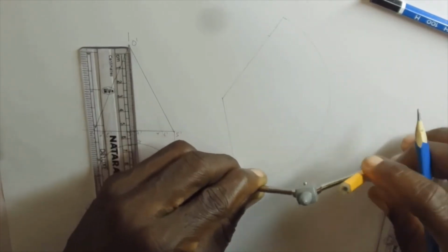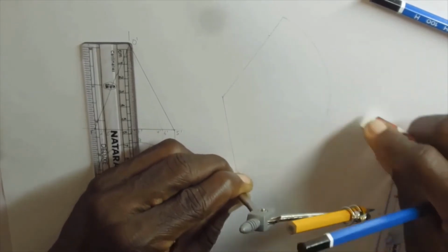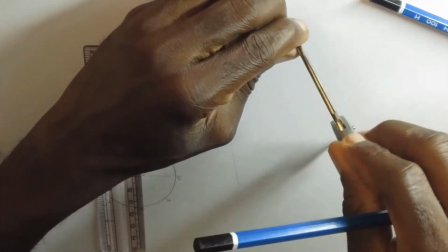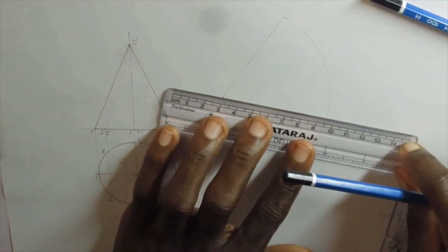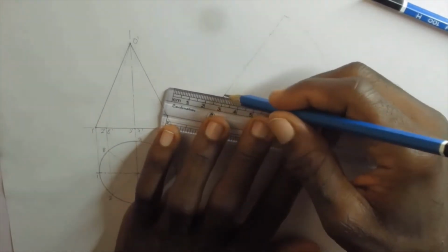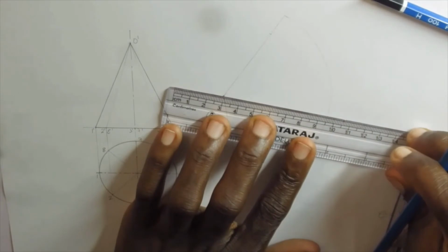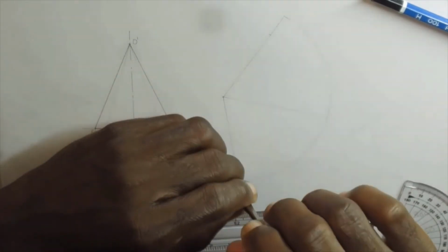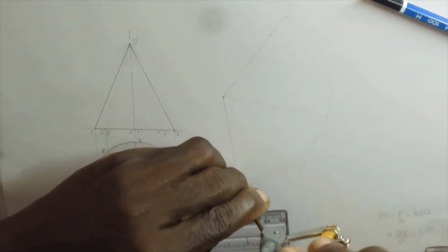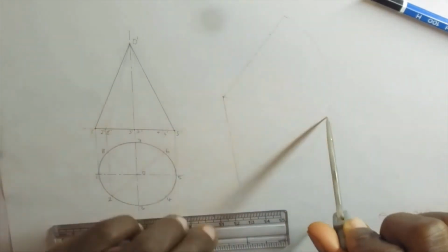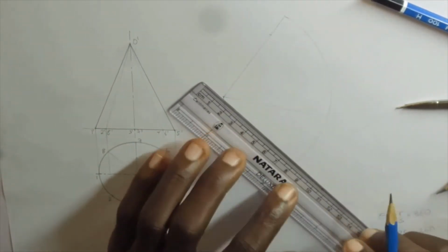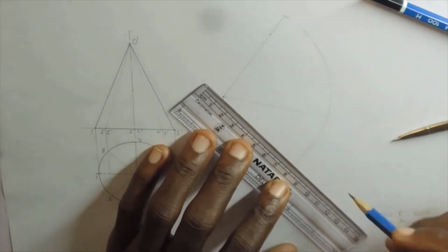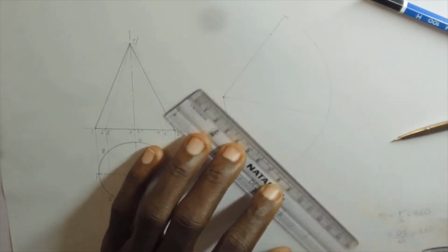And the easiest form is that we use your compass and we bisect. First of all, you bisect the angle made by the cone. So we bisect it that way. So when you bisect, you're going to have your bisector. So you draw a line from the apex O to the center of the arc to that point. You don't have to extend it to meet the intersecting arcs. Then you bisect again the other one, to bisect again that angle. So now you are having the second bisection of the angle that you obtain.